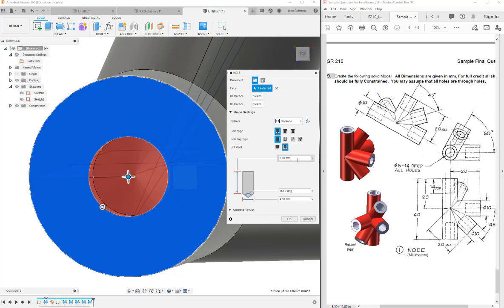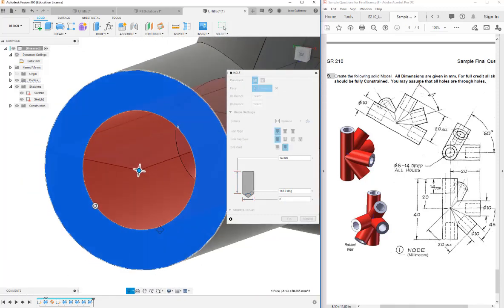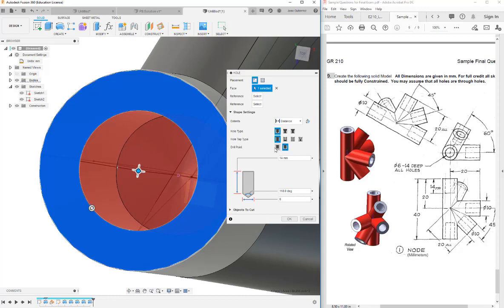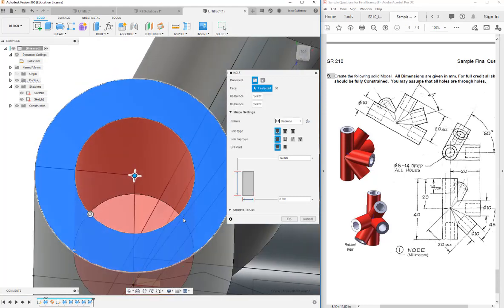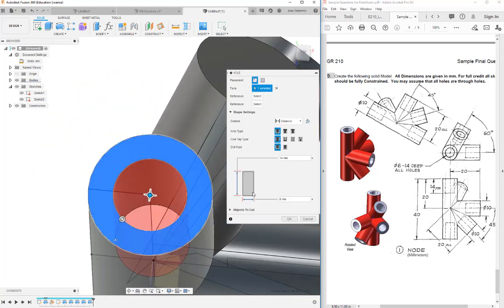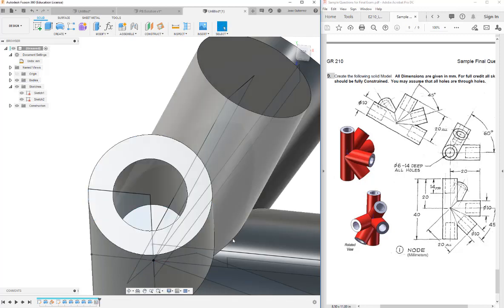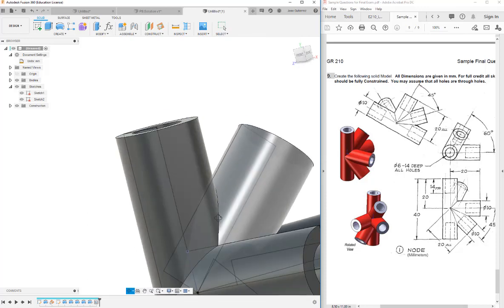The drill depth was 14, and then the diameter was a 6 mm diameter hole. Now this profile isn't going to look the same. Now we could change this to a flat profile. Typically this isn't a good way to make a hole with a flat end mill, but we'll just go ahead and use this design as is. So I can change that right there.